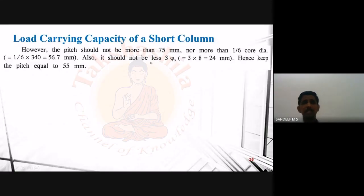Also, it should not be less than 3 times phi s, where phi s is the diameter of our helical reinforcement. 3 times 8 means it is 24. So it should not be less than this value. It should not be larger than 75 or 56.7, but again it should not be less than 25 also. Hence, we will provide a pitch equal to 55 millimeters because we cannot go with a value larger than 56.7. So we will stick to 55 millimeters.